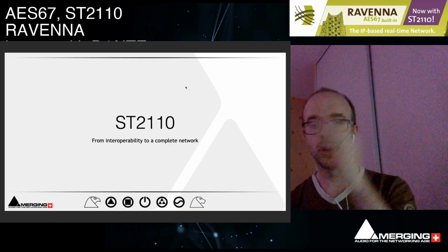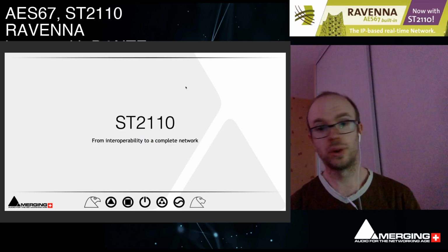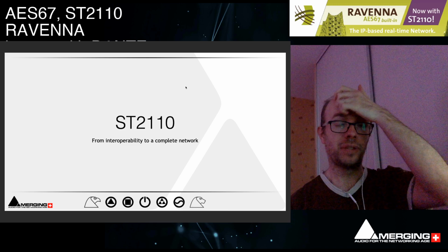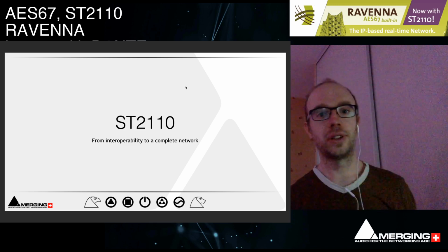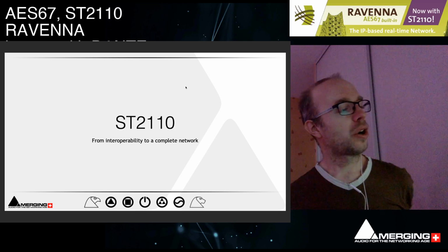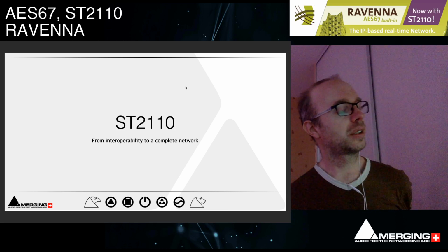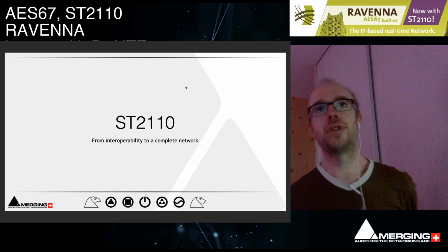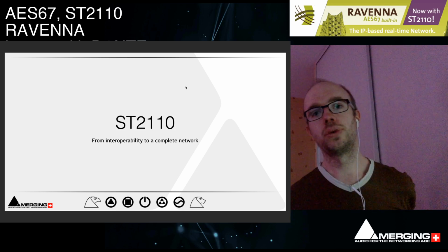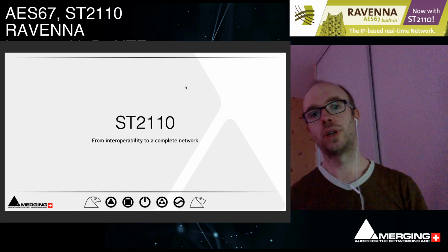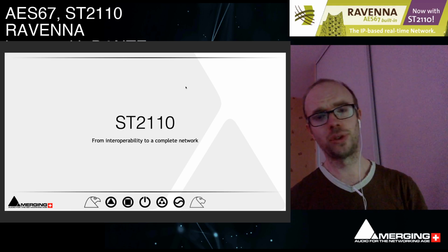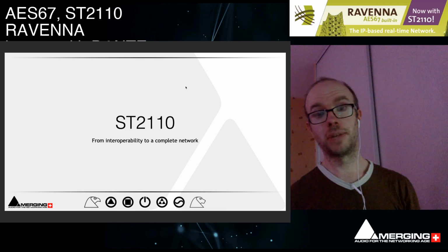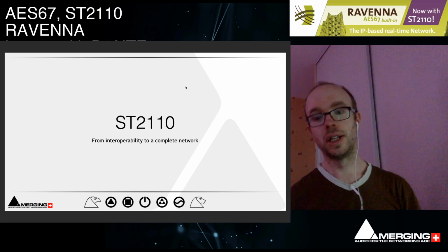Okay, so there's not only AES67 but also other protocols. AES67 is based on interoperability, and it's a damn good protocol. And at the SMPTE, when they tried to go beyond ST 2022, which was SDI over IP, the problem with SDI over IP was that even an audio device would have to be fed the whole SDI stream to be able to just extract the audio channels. And this is obviously problematic because when you try to do 4K, you are easily above 1 gigabit, but even over 10 gigabits of data per second.